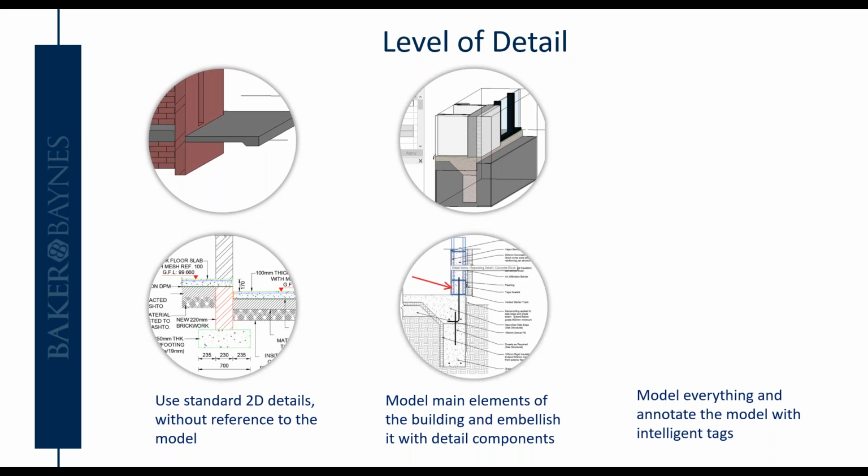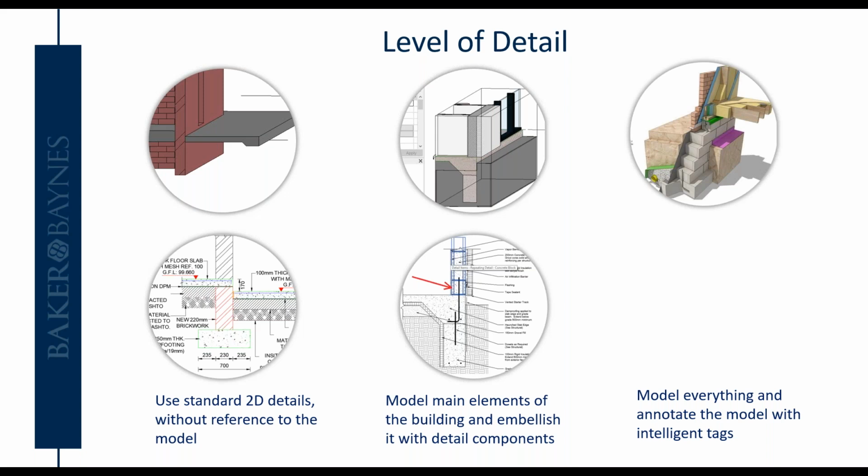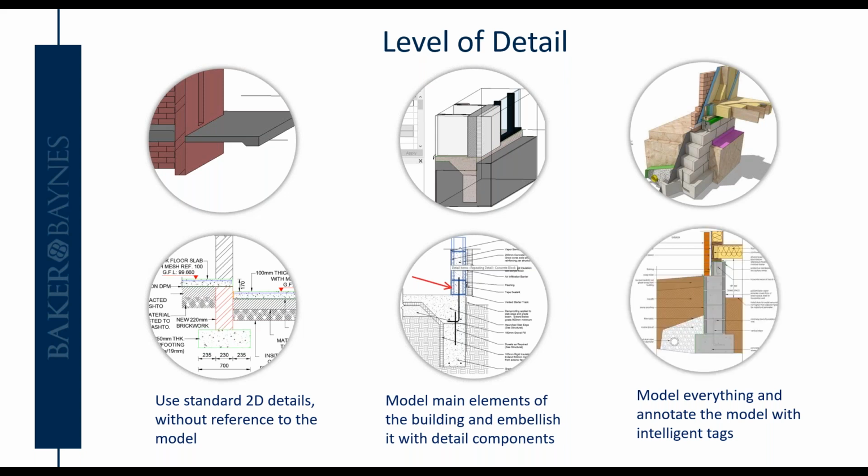And so you've got, for example, the rebar that you're seeing on the detail is not modeled inside the model. It's just a detailed component that you add to your drawing that has got some intelligence attached to it, so that when you tag it automatically, that information is right there. And then the third option was everything is modeled, every single tag is intelligent, and if you change anything in the model, the tag will update as well.